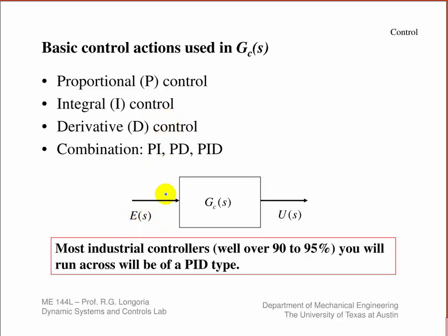And so the proportional action obviously looks at the error and gives you an action that's been proportioned to the error, and it tries to reduce that error, and we'll look at that. If you understand the PID and how it's put together, it gives you a good understanding of most controllers that you're going to see in practical applications. So it's worth having a good understanding of that.